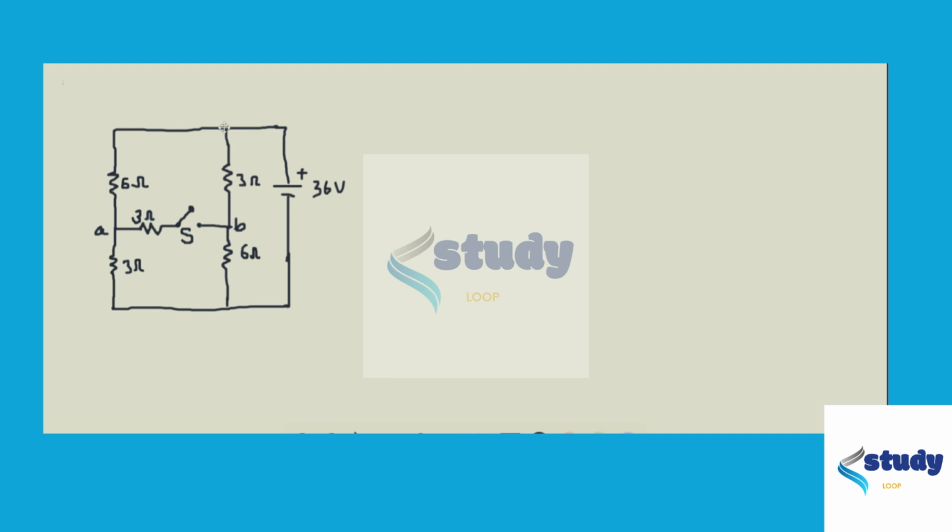So both of these branches will have the same 36 volts of EMF across them. In between, the ratio of resistance is 1 is to 2, so the ratio of voltage across these resistances should also be 1 is to 2.